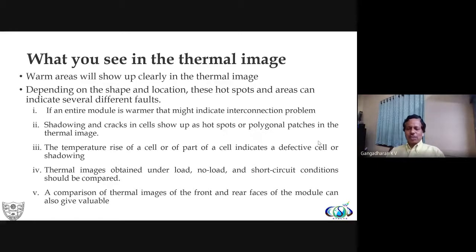A comparison of the thermal image of the front as well as the rear of the module can also give valuable input. But the problem is those are on the rooftop. We found it is pretty difficult because it will be kept on the roof. The bottom portion thermal imaging is going to be difficult because even if you have, say, a 1 foot gap, you cannot keep a camera below and click a picture. Whereas we need a slightly higher distance.